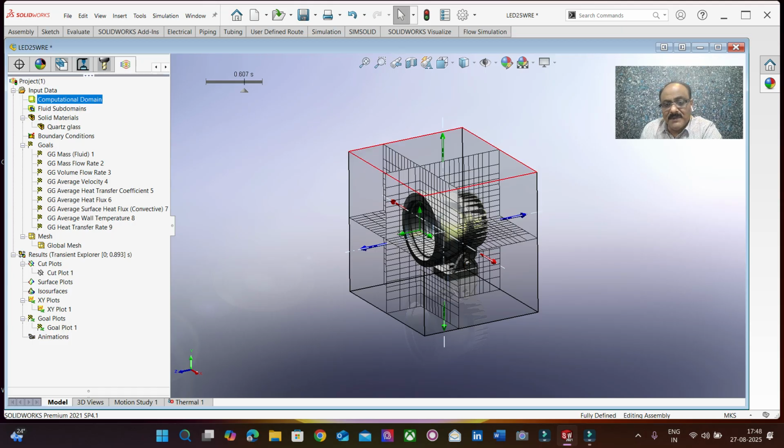So what you see in each plane is going to get integrated over that particular volume. It's very simple to understand the logic. On each plane we have the meshing, and each cell, each rectangle you see here on each plane, is going to get integrated over the next dimension, that is the thickness.